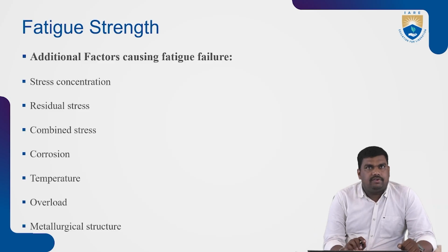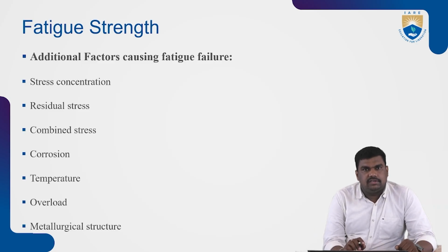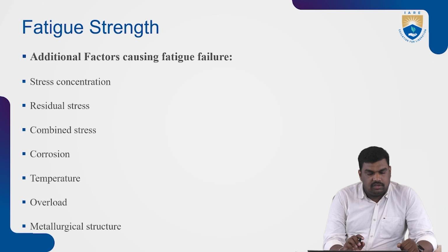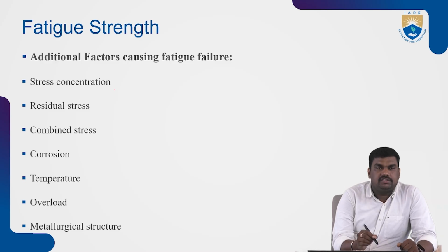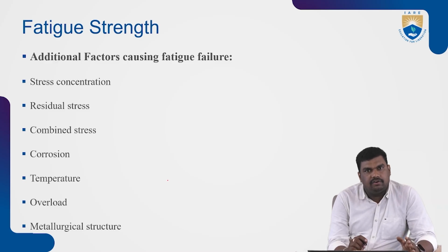The additional factors causing fatigue failure are stress concentration, residual stress, combined stress, corrosion, temperature effect, overload, and metallurgical structures. Stress concentration, as I said, occurs when there are undulations, sharp corners, notches, or small scratches or cracks over the surface.